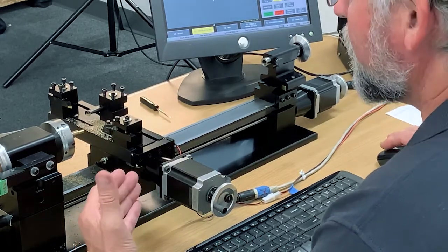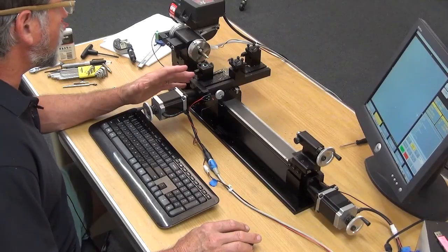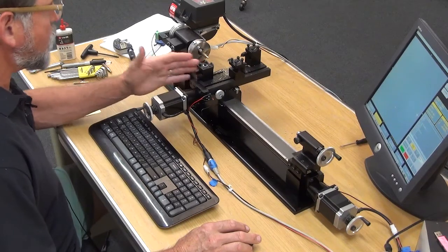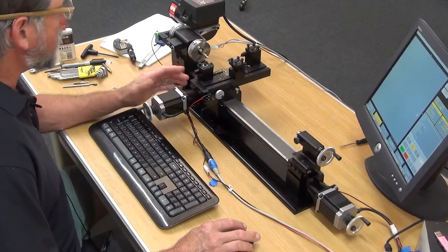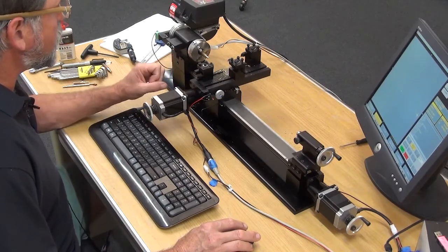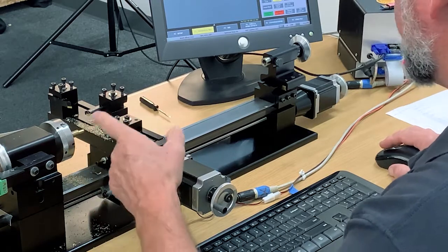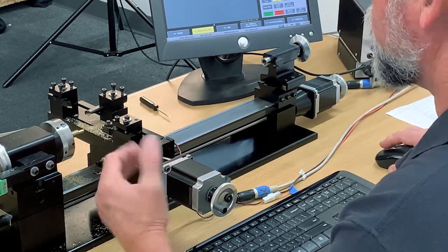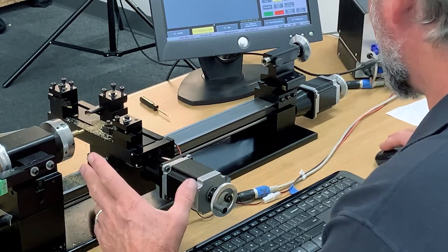So one of the advantages of having a short finished threading program is your thread cycle might be 20 passes on a thread. Okay, if you have a finished threading cycle, which is doing just two finished passes, then what we can do is walk in the offset and just rerun the finished threading cycle until we get the thread on size. So right now we have the finished threading program up.